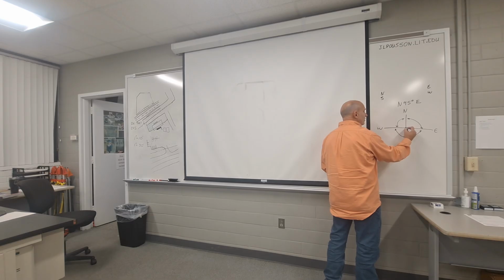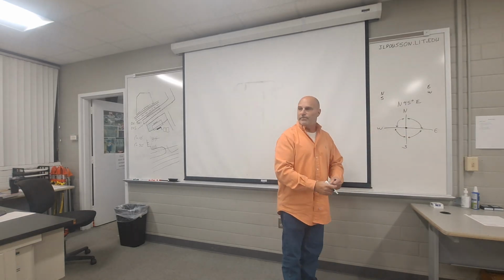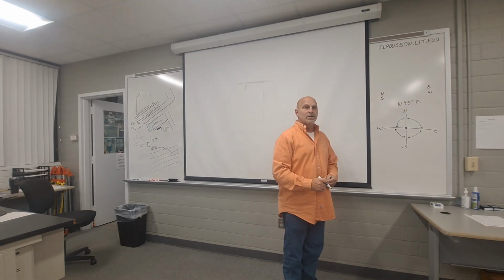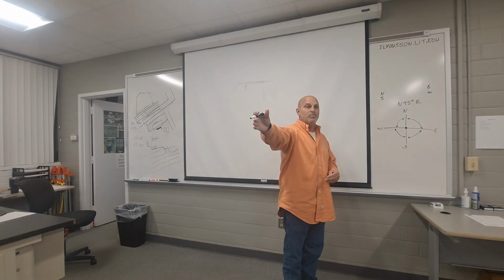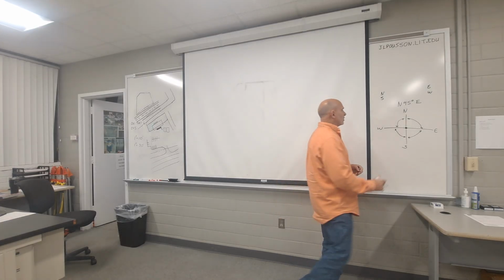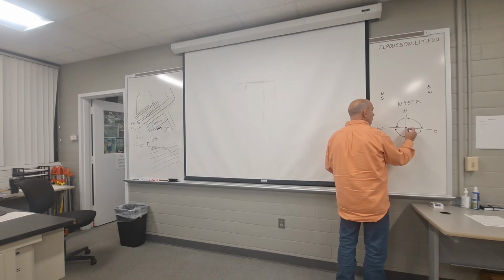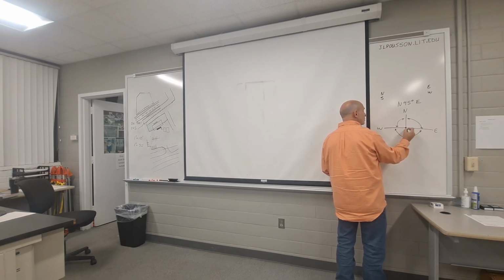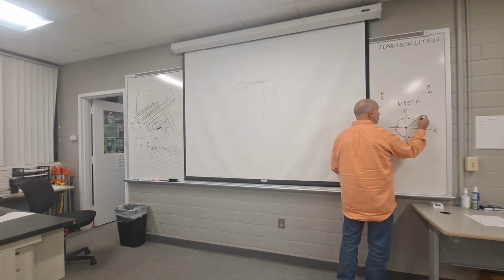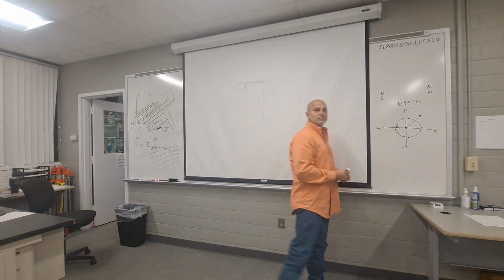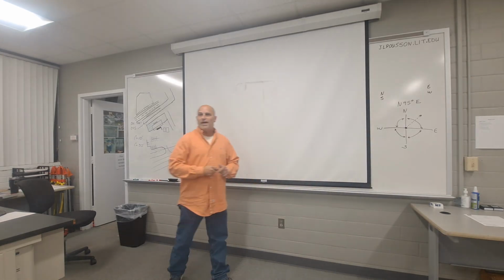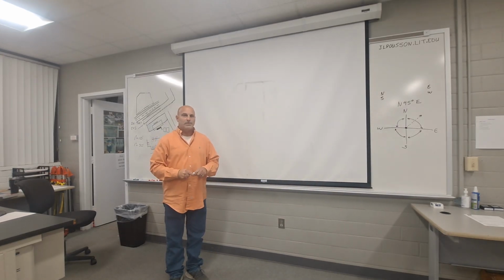If I say, okay, you're out there, maybe they're standing at the starting point and they're fixing to lay out this property, and I'm telling them how far to put the next property in. I'm gonna give them a distance and then I'm gonna give them a direction. What they're gonna do is they're at that point, just like in the other classes, you're at the center of this one. They're gonna face north and they're gonna rotate to the east 45 degrees. That's what that angle is telling us.